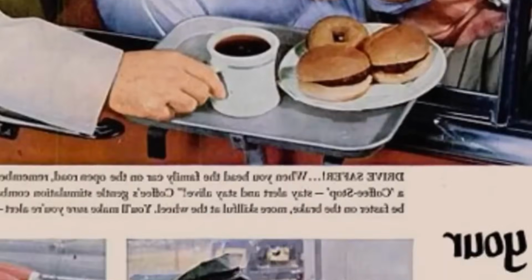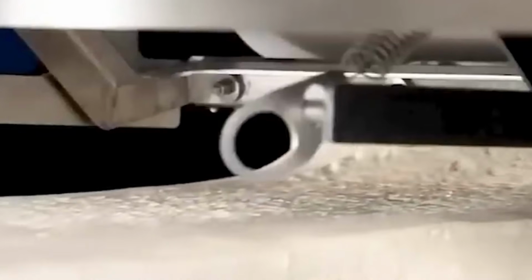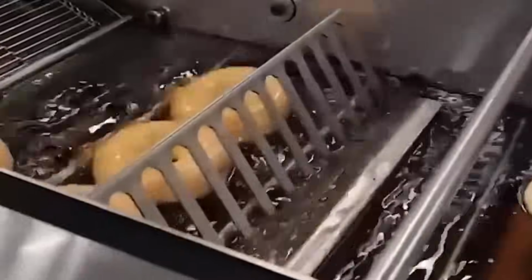Post-decoration, all donuts pass through a spiral cooling tower. This vertically stacked conveyor system allows compact, high-capacity cooling with continuous airflow. Residence time is typically 15 to 20 minutes, allowing toppings to set and fillings to stabilize.